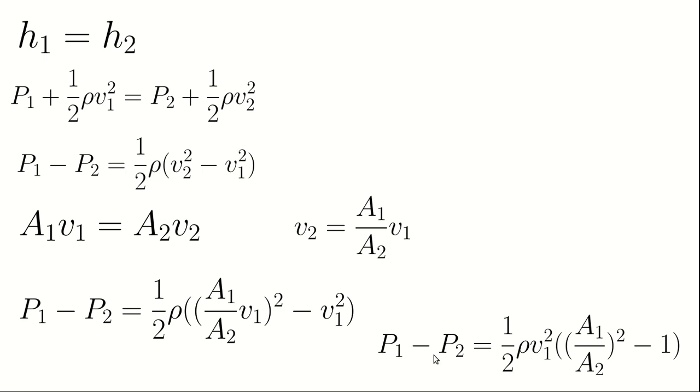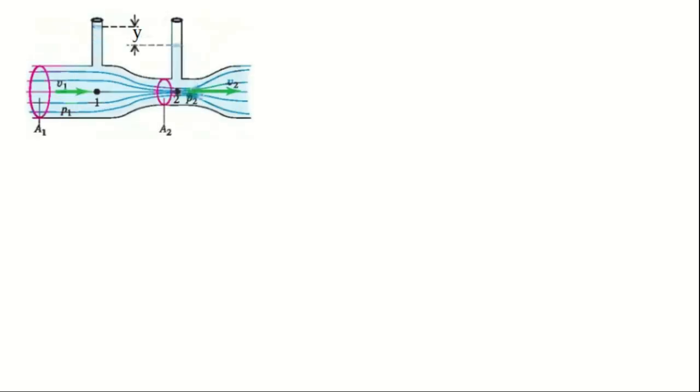But in a situation where the device that measures pressure is not at those two points, those two pipes, then you can replace your P1 and P2 with another expression. Okay, so let's come back. Let's see how we can replace our P1 and P2 by another parameter. Now the pressure at this point is giving us rho g h, which is this height, plus the atmospheric pressure, while the pressure at this point is giving us rho g h plus the atmospheric pressure at this point, right?